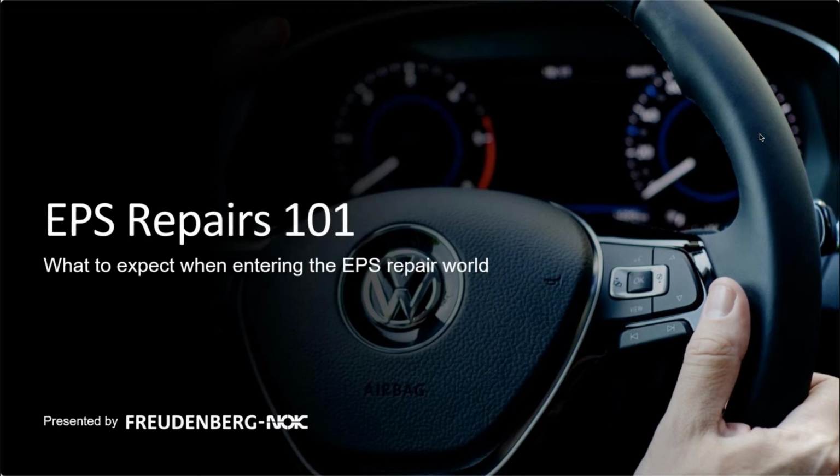Hi, good afternoon. If you have an error code in the steering, I would not sell the rack. First of all, I would double check that the parameters you have are correct. I'll review that the values from the Newton, so the torque and the position values, are changing the same as the voltage and the amperes. I would double check that information.